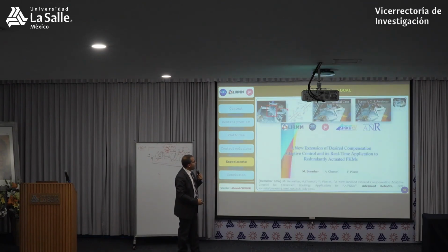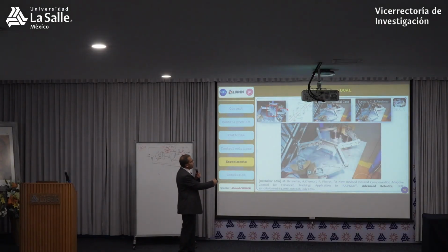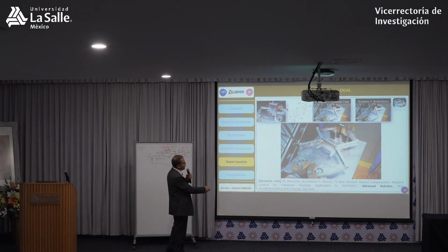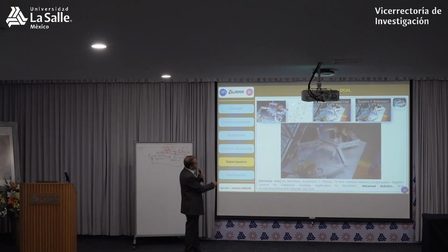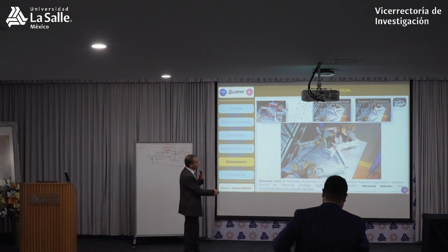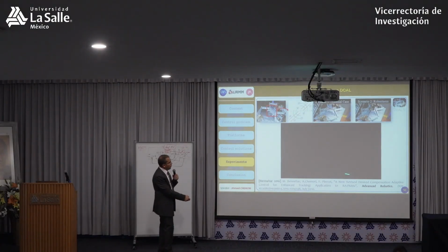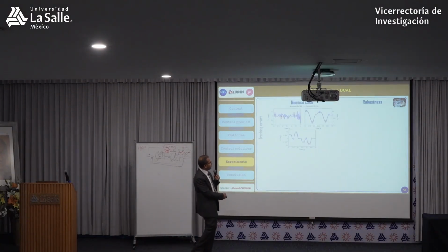Anyway, let's go ahead. Another result: you have seen DCAL, the direct compensation adaptive law. We proposed an extended version. We tested this on the dual robot here, and we tested these trajectories here, moving. The second scenario was adding a payload which is unknown. We add this payload and we try to repeat the same trajectories to test the robustness of the controller. Also the same in the paper, you can find the details.